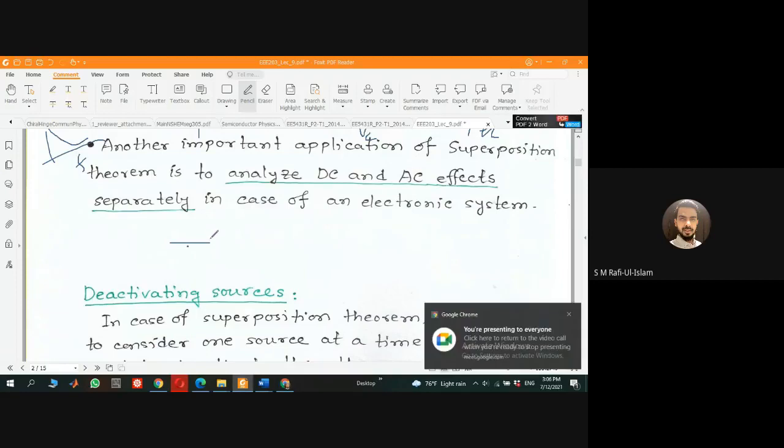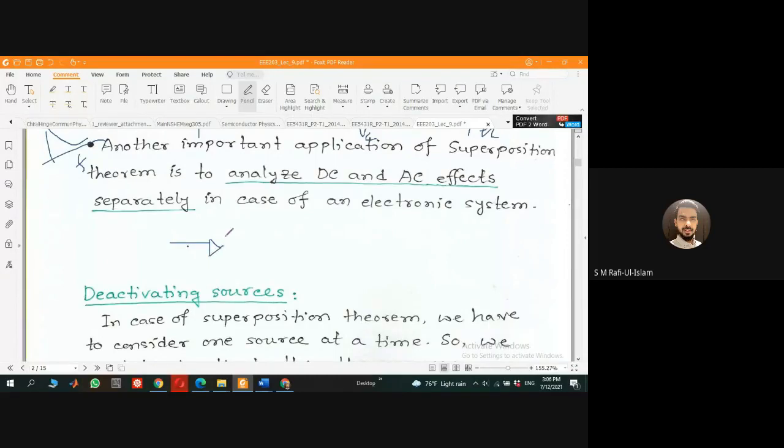So the thing is, if I have a diode, let's say we have a diode, something like this. So now I want to know what is the current voltage relation. So the current voltage relation, I equal, let's say, some constant that is written as Is. So this is called some sort of actually reverse saturation current, and then exponential term e to the power V, or whatever that voltage across diode, divided by kT, where k is the Boltzmann constant.